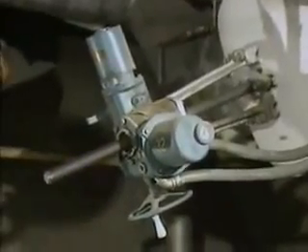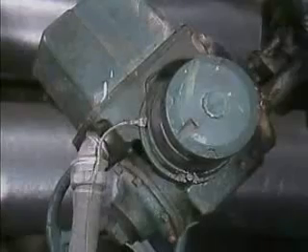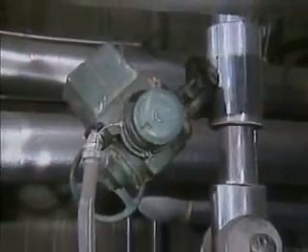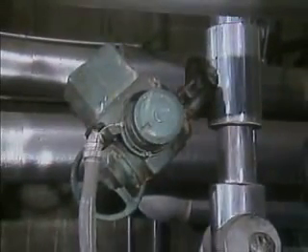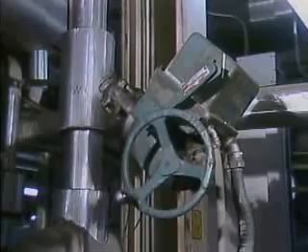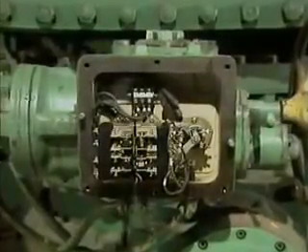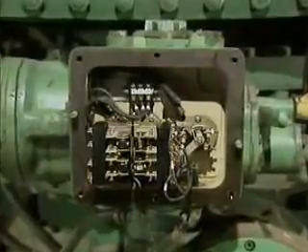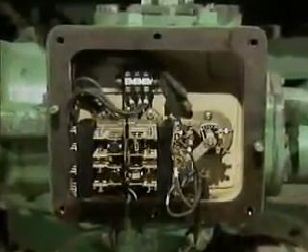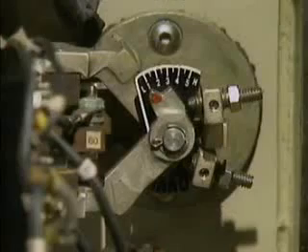Valves that have to be throttled often use operators that are driven by electric motors. The electric motor drives a set of gears that controls the travel of the valve stem, which, in turn, positions the valve. When the motor is energized, the valve stem begins its rotation to raise or lower the disc. Enclosed in the body of many electric motor operators is a torque switch, a limit switch, or both, to ensure that the valve is positioned properly without being damaged.